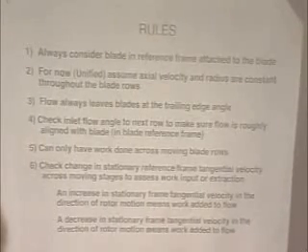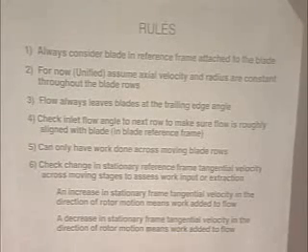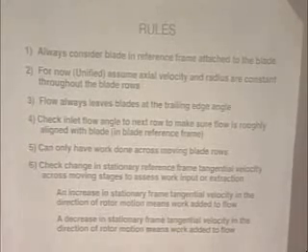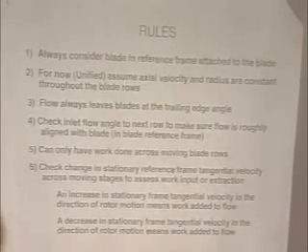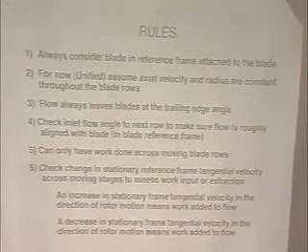Always consider a blade in a reference frame attached to the blade. So if you're in a stationary blade row, make sure you're in the stationary reference frame. If you're on a moving blade row, transform yourself into the rotating reference frame. That's why you have to change reference frames every blade row through the compressor.